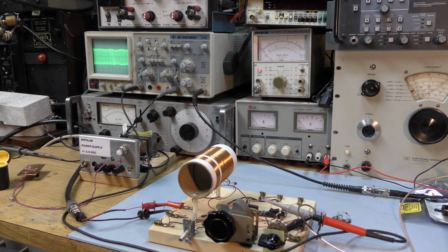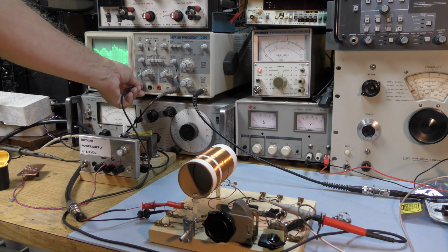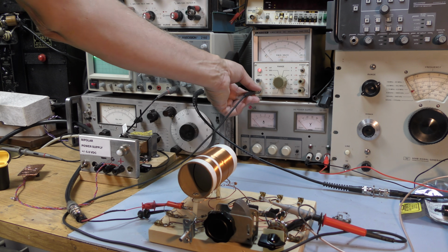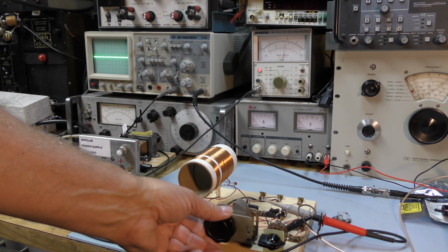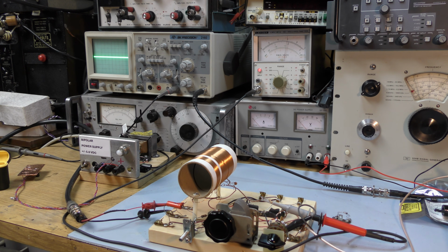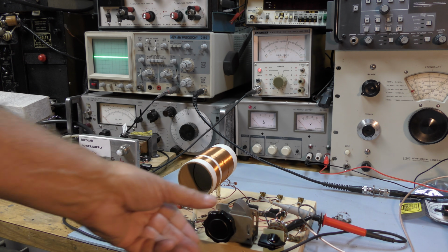Let's look at the strongest signal. It looks pretty strong, but I am on the 5 millivolt per division scale. 5 millivolts. Let's look at the RMS value. This is a ×1 probe, and a 10K resistor is in place of the diode. Let's just tune. So it looks like it's 6 millivolts RMS, and that's the strongest signal on the band.